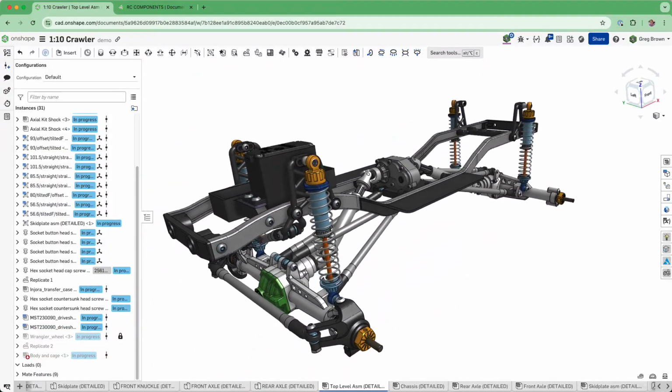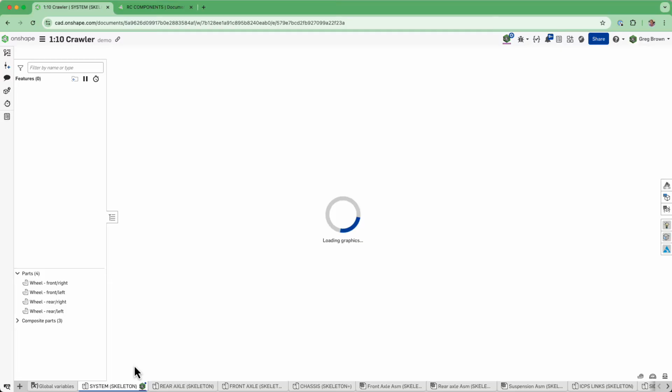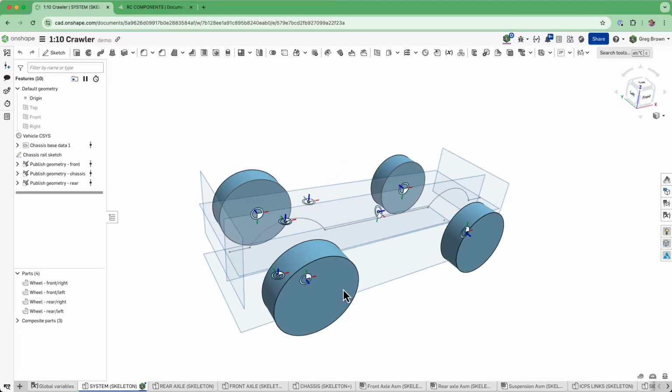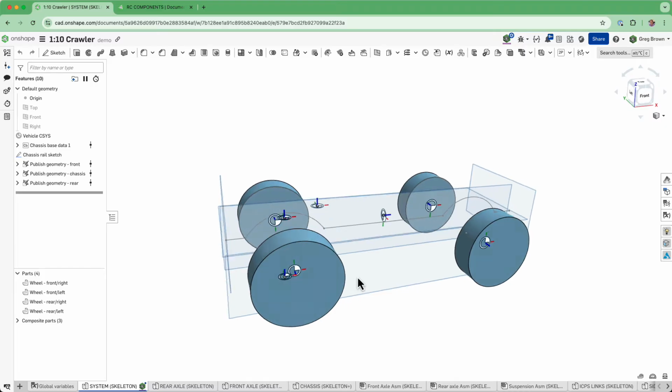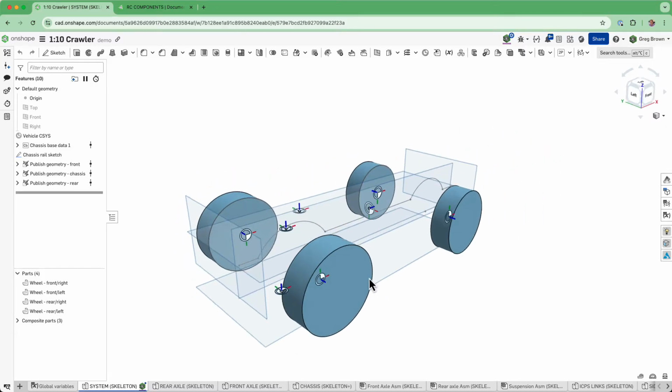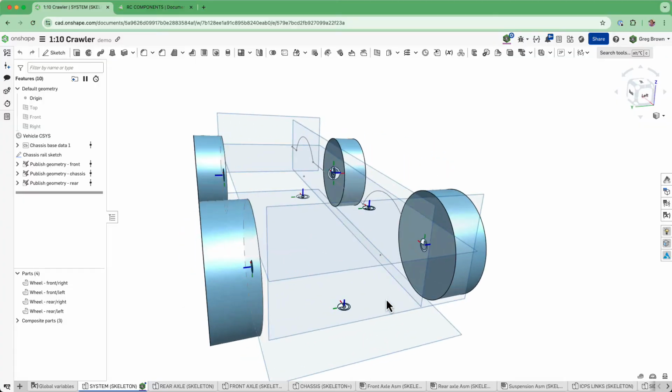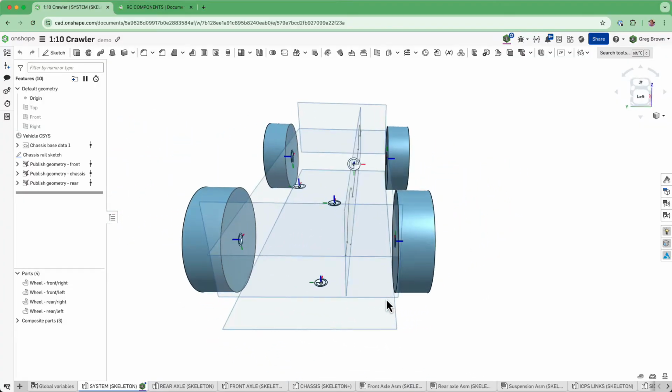And by the beginning, I really mean all the way back here. In fact, let's call it a system level skeleton. I like to use these kinds of skeletons and flow things down top down as much as possible. Whether you're doing a vehicle chassis like this, with lots of linkages, or some kind of robot or machine or just about anything which has a complicated assembly, these techniques apply equally well.